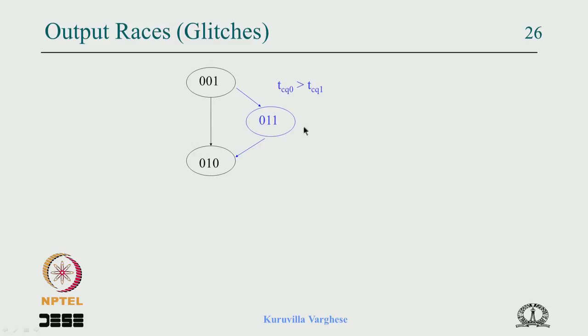It becomes that for a very brief period. Don't worry about it. We talked about this in combinational circuits: when there are multiple outputs, there is a difference in the path delay, and it happens. Similarly, when there are multiple flip flops, because of the variation in the propagation delay of the flip flops, this happens. It is very natural. Okay, there is nothing wrong with this.